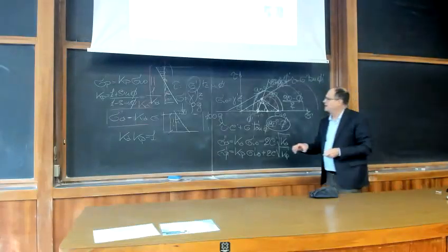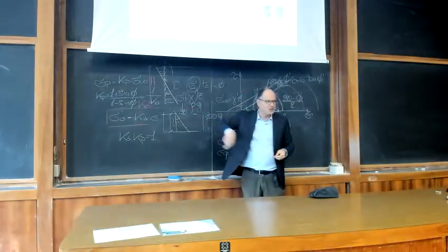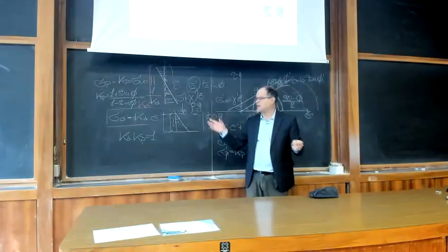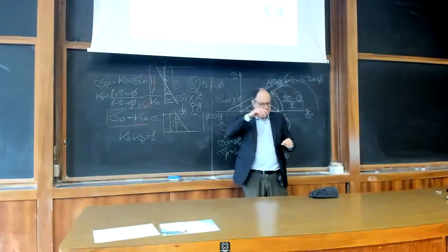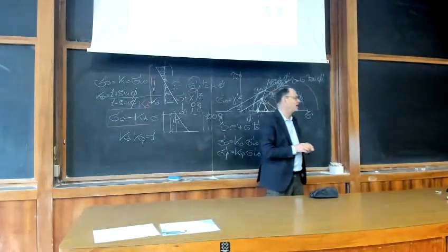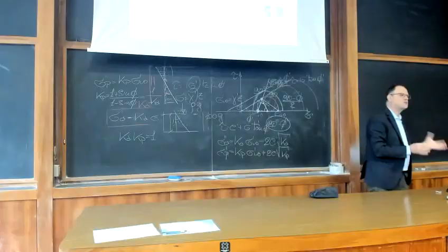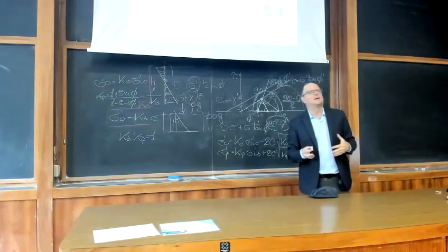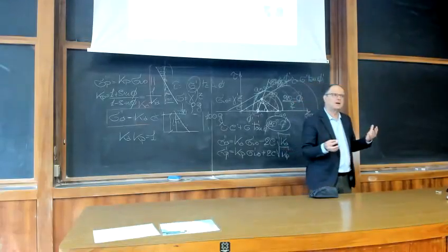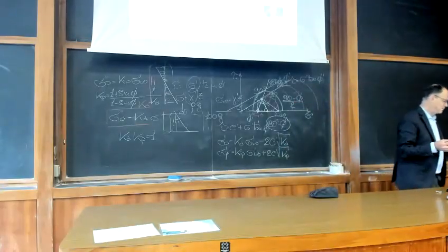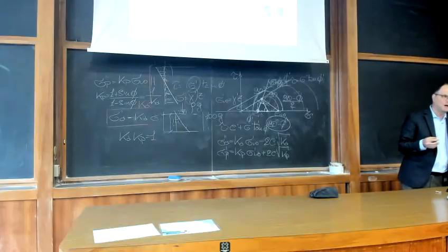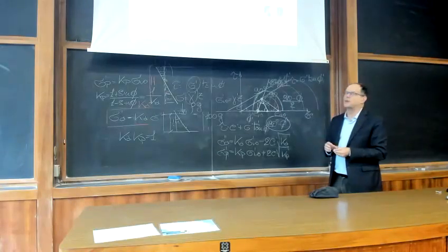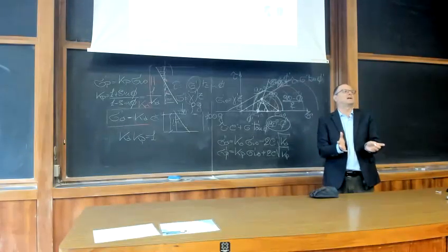You have to load your footing while still spinning, and you have to measure settlement and apply any load while you are spinning, and it is quite a sophisticated, quite an expensive piece of equipment. Only few laboratories can have a centrifuge. In Italy we have only one centrifuge in a laboratory in Bergamo, and it's not the typical piece of equipment that you can have in a laboratory.